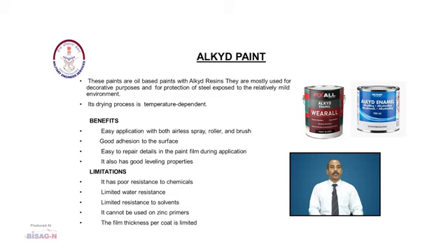Benefits are easy application with airless spray, roller and brush, good adhesion to the surface and good penetration properties, and easy repair of details in the paint film during application. It also has good leveling properties, but this paint has certain limitations. It has poor resistance to chemicals, limited water resistance, limited resistance to solvent. It cannot be used on zinc primer and the film thickness per coat is very limited.